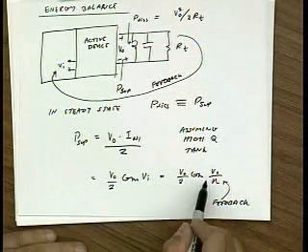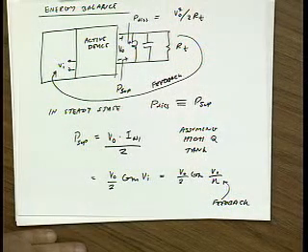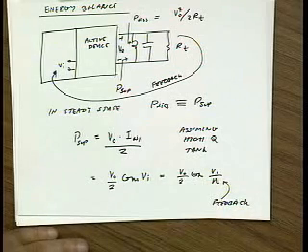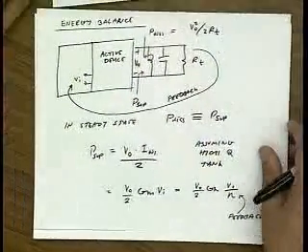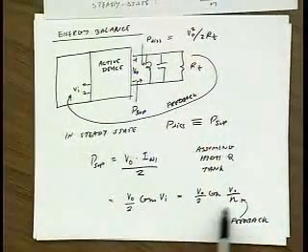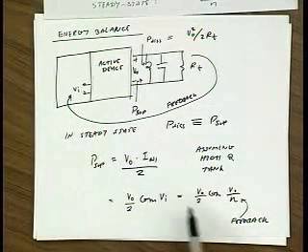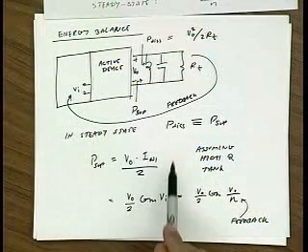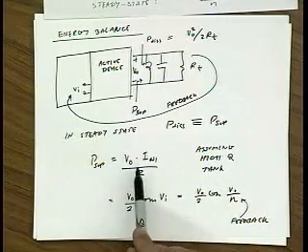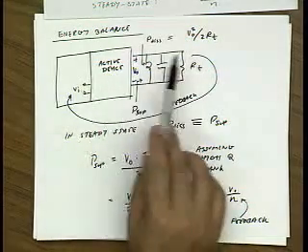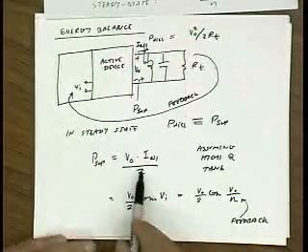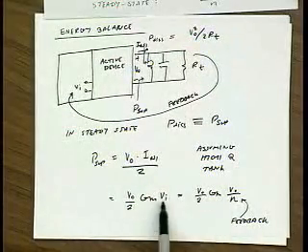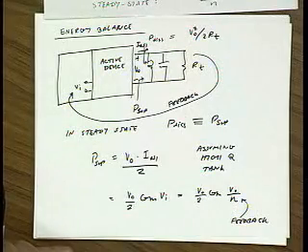And I'm assuming that the input is in phase with the output after being multiplied by GM. So if GM were negative, like a normal transistor, then the feedback would have to be negative as well. Otherwise, you can see immediately that this won't work. It won't be able to supply power to the circuit. So to keep this quantity positive, in the sense that if we define the current coming out as being positive, so this is I omega 1, then you can see immediately that GM times V in has to be positive. Okay.